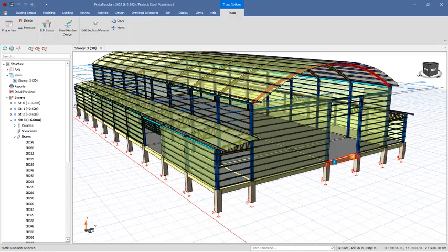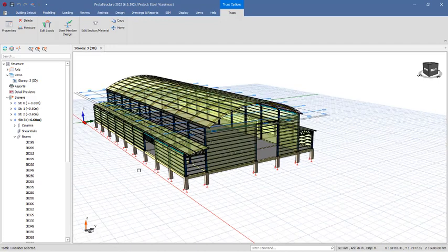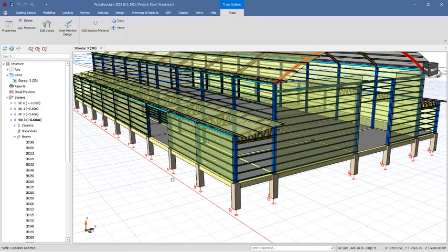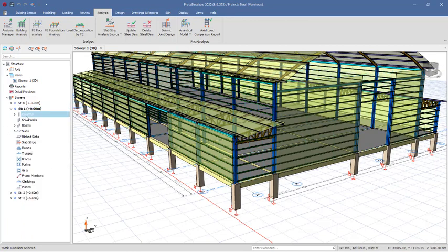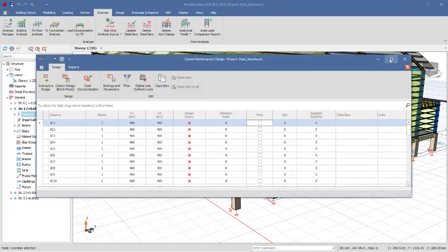All right, so coming back, for the reinforced concrete columns, you can now select on this, and then we have it at story one, so you have to navigate to that story one. Then you select the column, right click, and click on RC columns slash wall design. You will have a dialog, and you notice in the dialog that all of the columns have not been designed because we did not ask the program to design them.